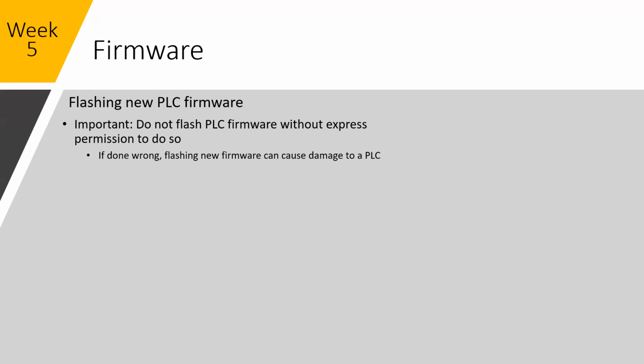If you do it wrong, you can brick. By brick, I mean you literally turn the controller into a paperweight or a brick. If you start the upgrade process and it doesn't finish properly, if you lose power, you can damage these controllers. It's not super common. I've only done it to about 5 and not in a long time, but on some of the older ones, you can damage them.